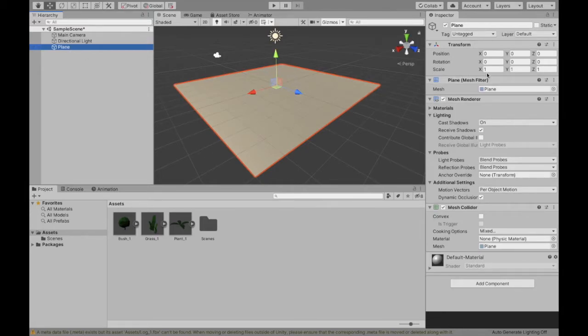So here the scale is still just 1. So let's say your scale for your plane is about 1,000. This tool may not work. If it doesn't work, it might be because of the size of your plane, and you might want to just either create a bunch of smaller planes or just change the size. And so the tool is Polybrush.